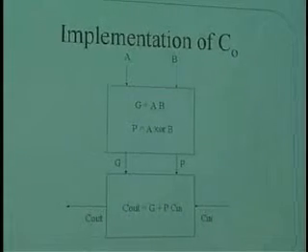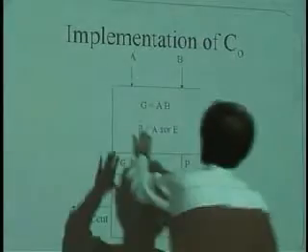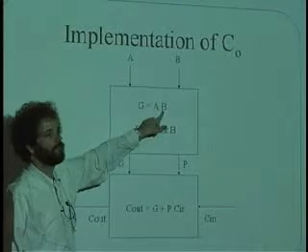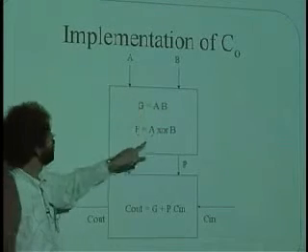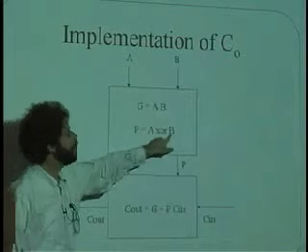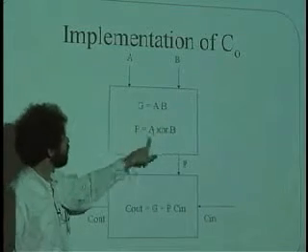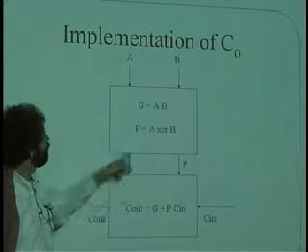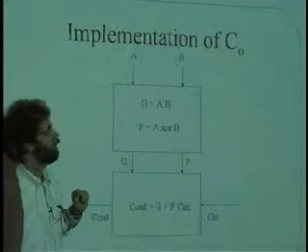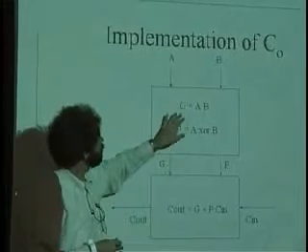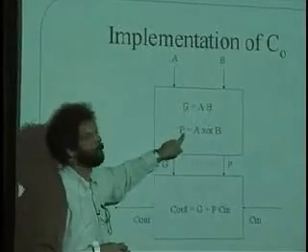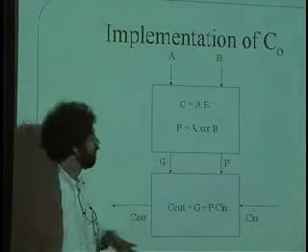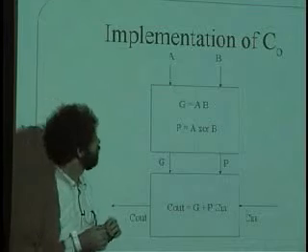And it looks like this. Okay? We have a preprocessor to generate G. Generate. If A is true and B is true, then generate the carry. If A is true XOR B, and again, this computation takes place before C sub in comes in. Pre-processing that's done, then we're going to propagate the carry. Okay? And we set these things up so that if the generate is true, this is false. Because when we generate, we don't really propagate, we just generate. We're sort of blind.